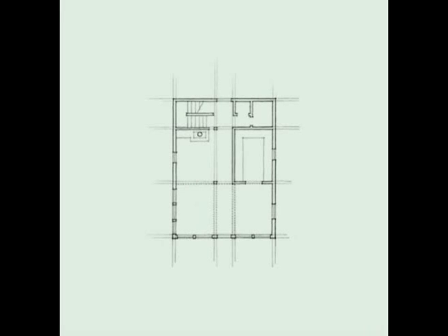Use intermediate line weights to delineate edges of surfaces below the plan cut, and the lightest line weights to represent surface lines. We typically give the cut material a tonal value that contrasts with the spatial field of the floor plan. We refer to this darkening as poché.